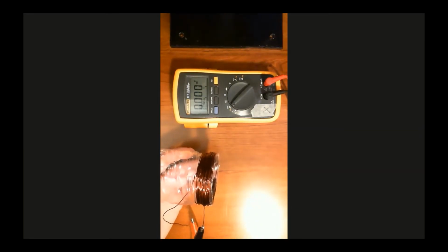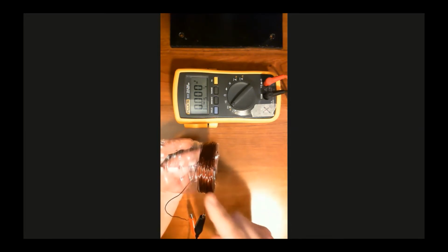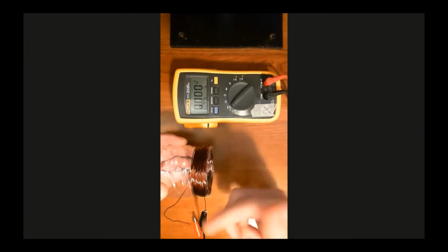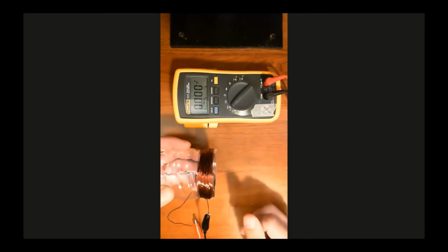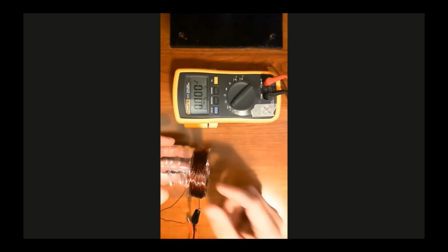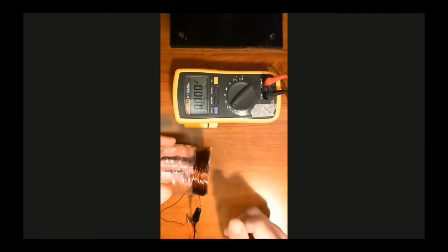All right. The one more thing that I wish I could show easily, but it's not easy to show. We could also change the amount of induced voltage by changing the number of turns or loops in this coil of wire. So if I added 50 or 100 more loops of wire, what you'd actually see is a larger induced voltage. And as it turns out, the induced voltage is actually directly proportional to the number of turns or loops in this coil of wire. So if I doubled the number of turns in this coil of wire, I would double the amount of induced voltage. All right, so that's what I wanted to show with that experiment.